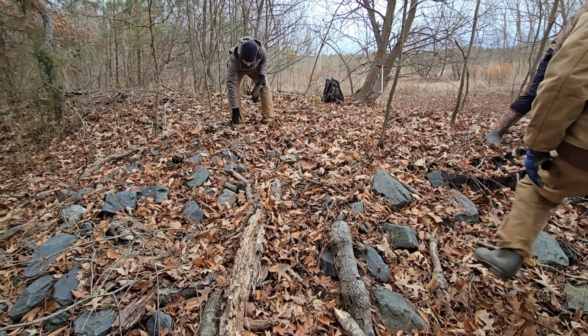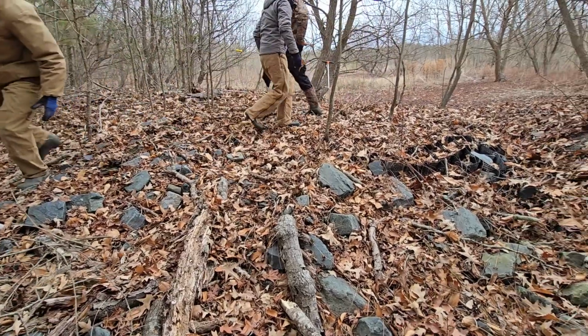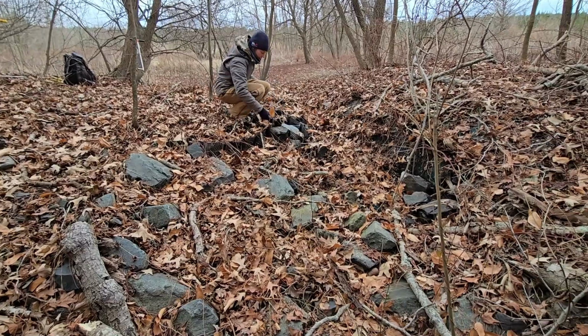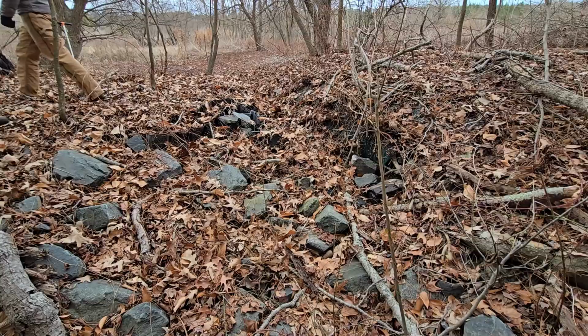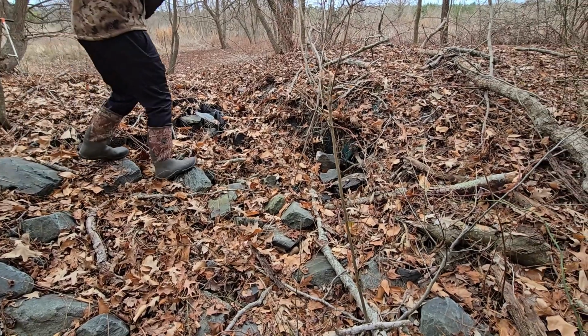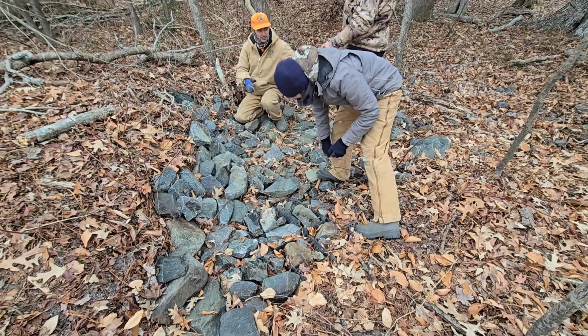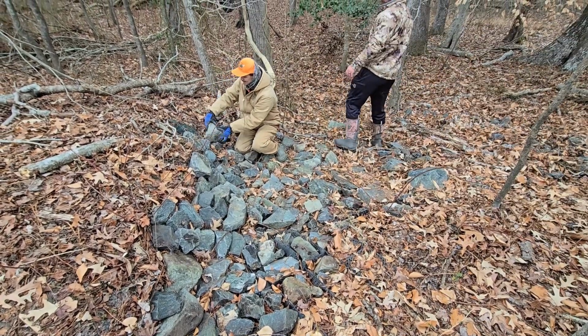The rocks must fit tightly together in the bottom of the channel and up the sides of the floodplain. It's also important to remove any logs or branches that have fallen in the spillway. Make sure rocks don't stick up high, as this will cause turbulence and erosion. The rocks have been placed so the spillway looks like a ramp. The bottom of the spillway along with the banks of the spillway are now armored with rock.